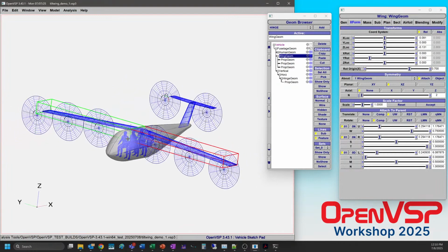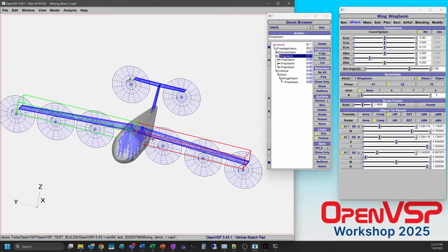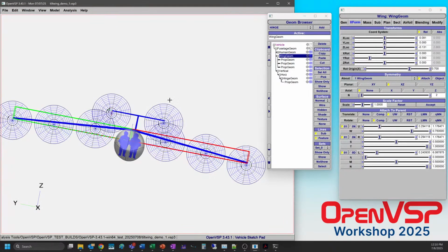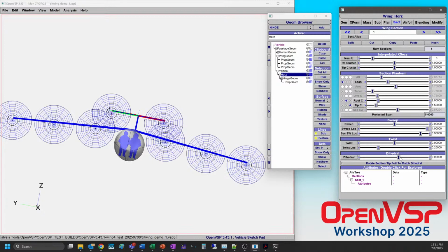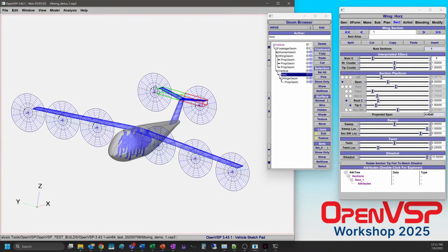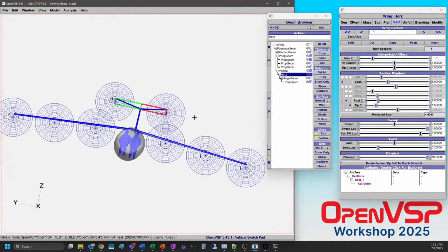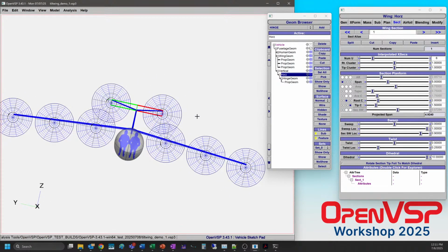So there's a number of ways that you can address this. You can either try not to disrupt the flow with the inboard rotors by spinning them very slowly, putting them into a low torque scenario. You can do all sorts of stuff. You could give yourself a bit more anhedral on this side, and you could even come into the horizontal tail, say, well, if we want them to move up, let's just move them up. No big deal. So there are a number of ways that you can try and address this problem, but note that all you have to do in OpenVSP is come in and change 1 or 2 parameters, and it changes everything for you if you set up your model correctly.